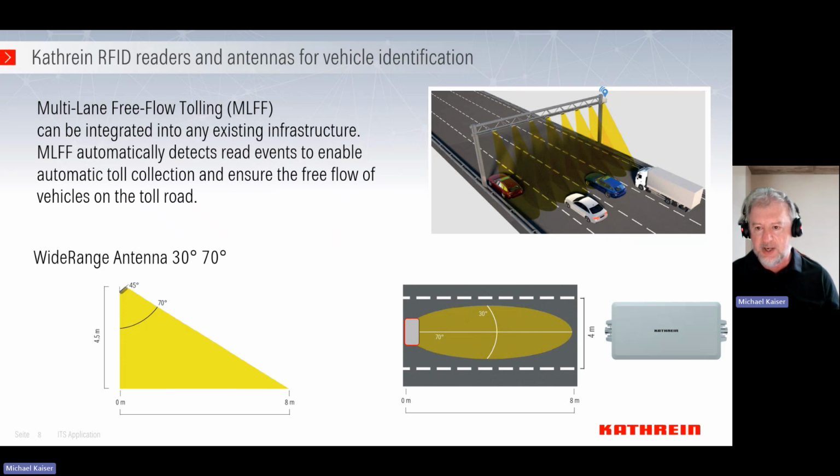And in the application, you see for each lane we have 1 antenna. We also have 1 antenna in between, and this really gives you a kind of reading curtain. It doesn't matter where the car is, you can catch them, and with the information from the antennas, you know exactly at which position the car has passed, on which lane the car has passed. Of course, you can do this on the motorway, but you can also do it on an entry area of the company ground.